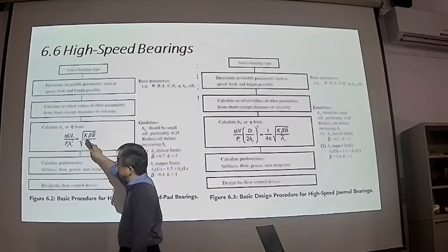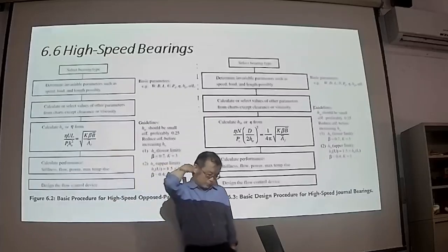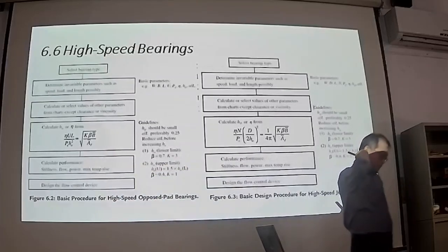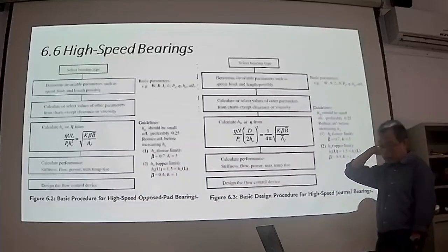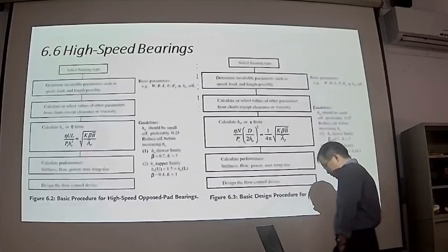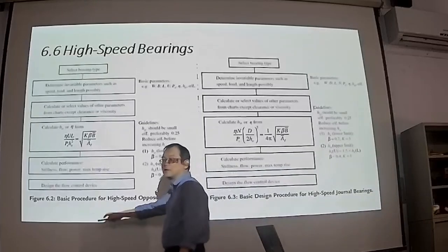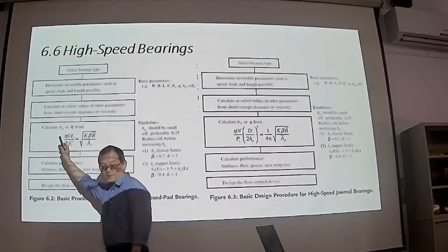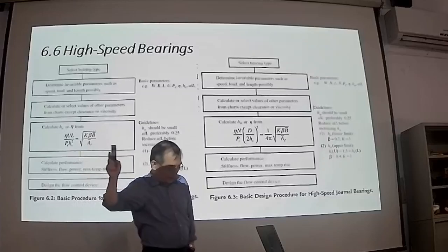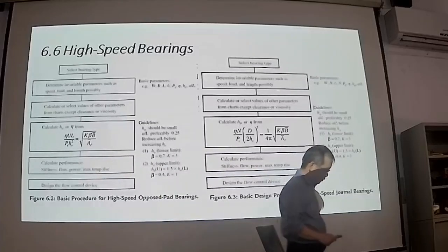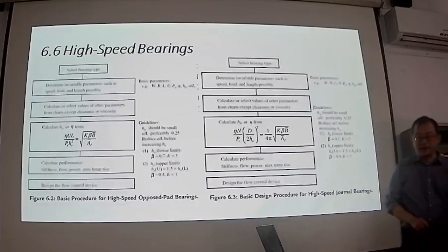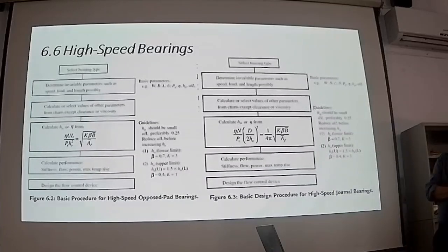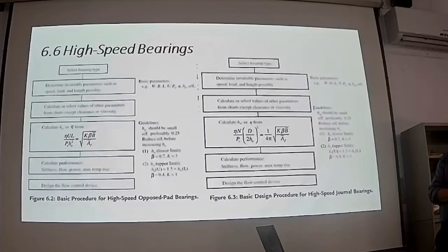Design lubricant, but usually the viscosity grade of the lubricant is not selected by calculation. Usually it's by taking reference from similar products in the market. Okay? So you know more or less your size of the bearing, and you know your operational speed.